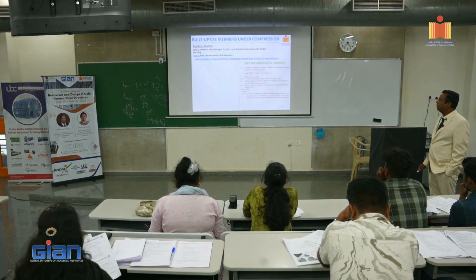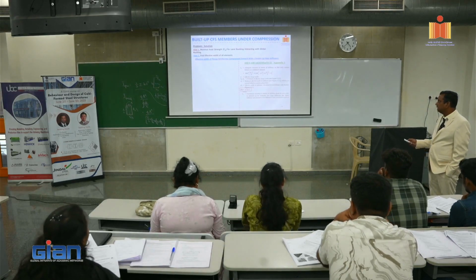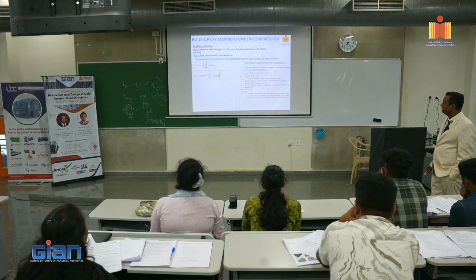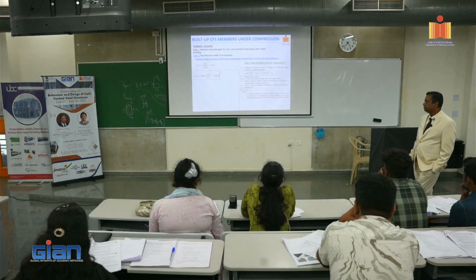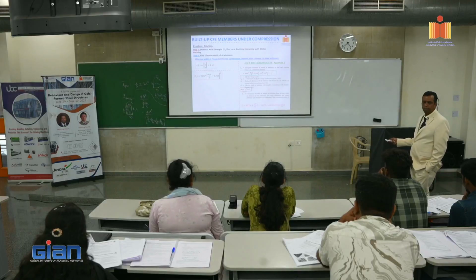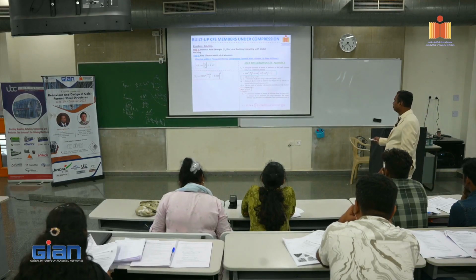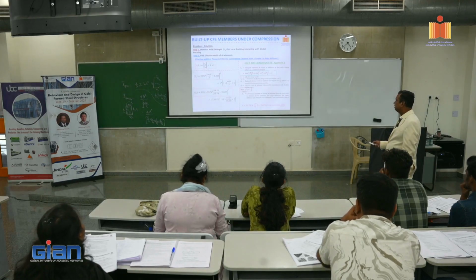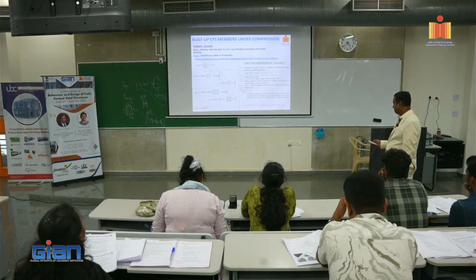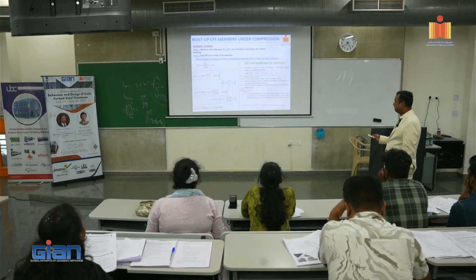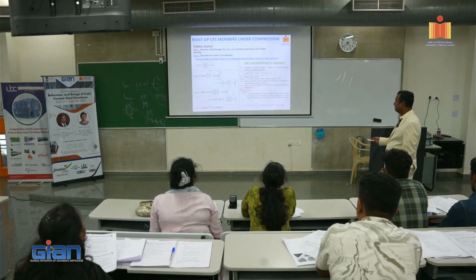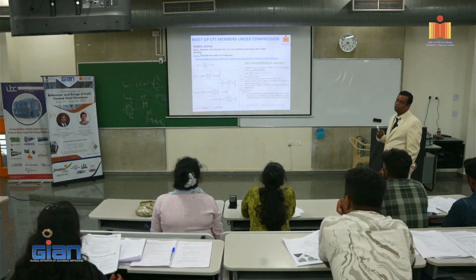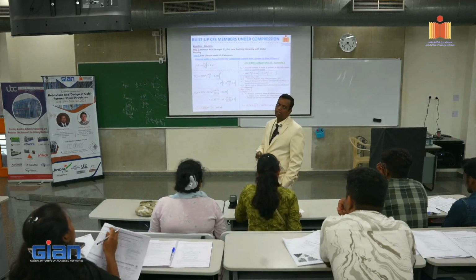So you have this equation, Is should be less than Ia. We have to calculate Ia first. Ia is given by 399 t^4 (W/t / S - 0.328) cubed. When we run the numbers, we know that S equals 35.78, and we already calculated W/t equal to 34.29 from the previous step. It should be less than this value also, right? So when we run the numbers, we get Ia equal to 1465.87, and it is less than 1689. So we can use this equation. Otherwise, we have to use only this one. It cannot be greater than 1. This number 1465 is less than this, so it is okay. So Ia equals 1465. This is what is required to act as a simple support so that k can be 4.